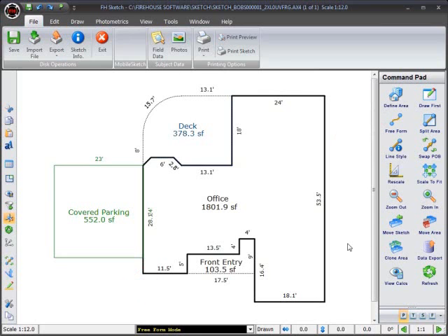Drawing in freeform is no different than drawing any line, with one exception. You can pick the pen up at any point and move your cursor to another location. The first line we need to draw extends from this point here to the perimeter wall of the area as indicated here. I'll move the cursor to the beginning point and press J to jump to it. Next, I'll press Enter to put the pen down, which changes the cursor from a pointer to a crosshair. The line is 18.1 feet in length. I'll enter 18.1 and press the right arrow. I'll press the Enter key to anchor the line.